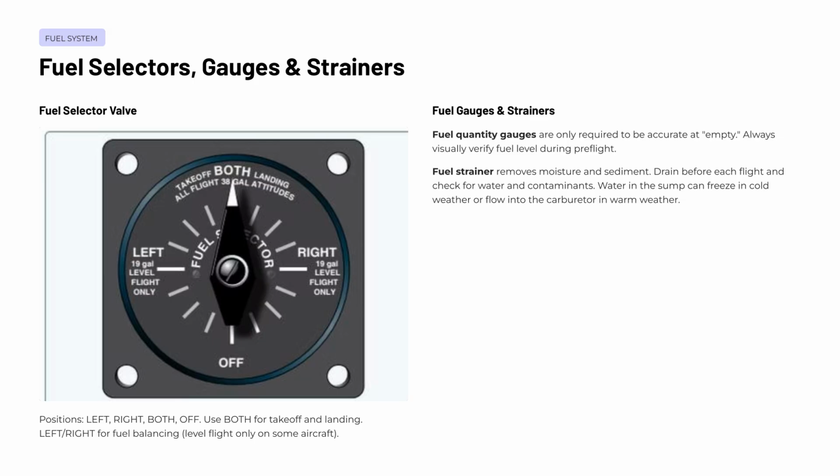Now, regarding fuel gauges, this is important. Regulations only require fuel quantity gauges to be accurate at the empty reading. That means a gauge showing a quarter tank could be optimistic. Never trust the gauges alone.